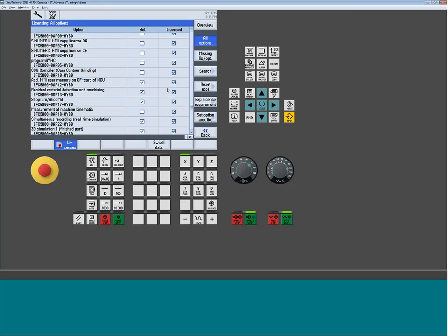You go onto a website. You type in that CF serial number I told you. You type in the option number, and it regenerates that number. You can physically type that into the control, and then the gray box will be checked. So for you to activate it, you then only have to come down to the white box, hit the select key, a little checkbox will be there, reboot the system, and then from there, those buttons will automatically appear.